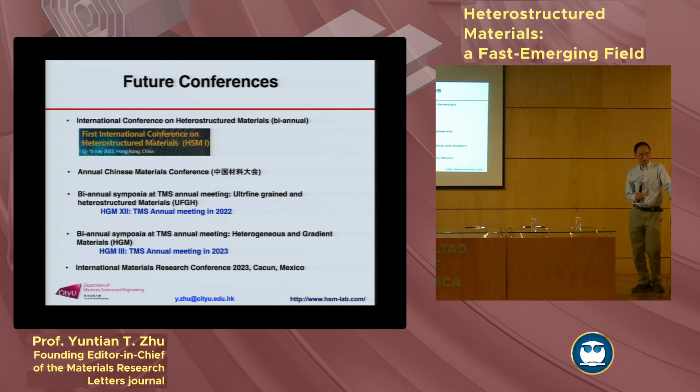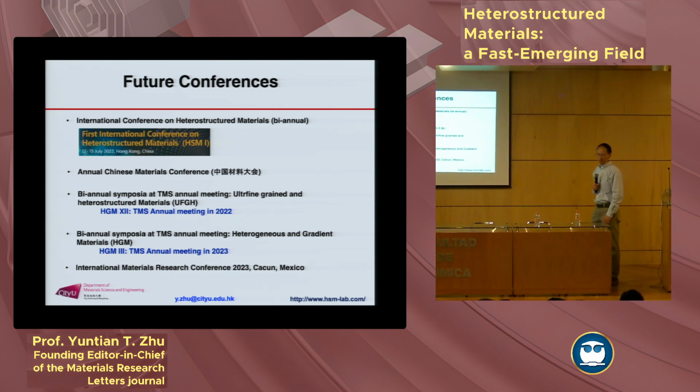For example, if you introduce such a kind of heterogeneous structure and apply it at high temperature, are there extra concerns we have to consider carefully during materials design, because you showed a lot of cases at probably lower temperature? Yeah, I think at a different temperature, you have a different mechanism. At high temperature, this dislocation pileup may not work anymore.